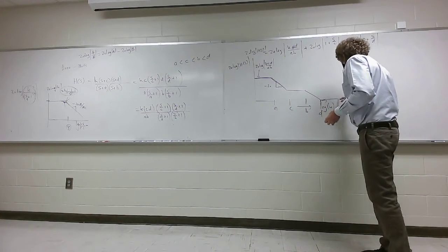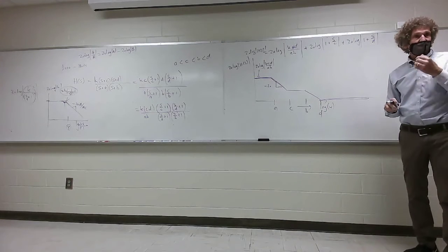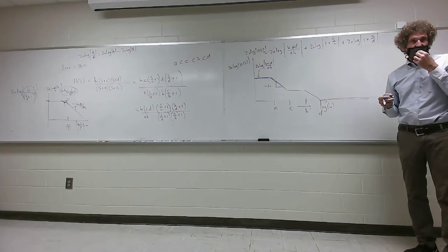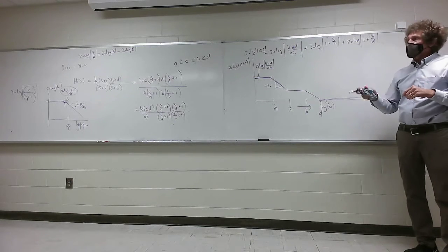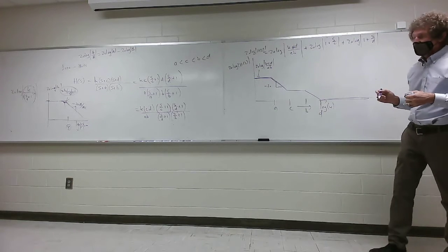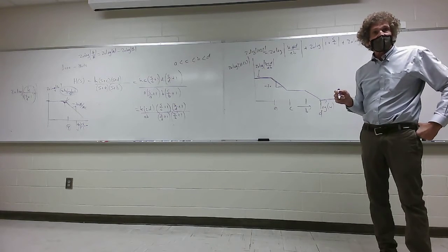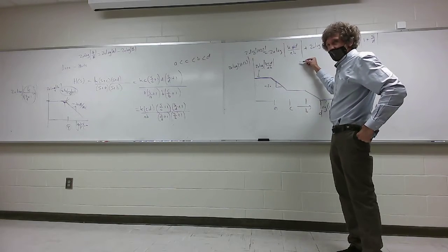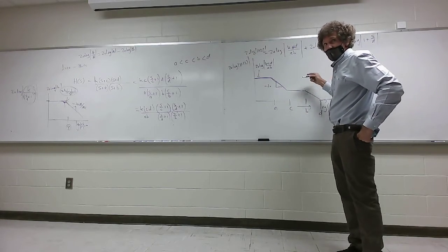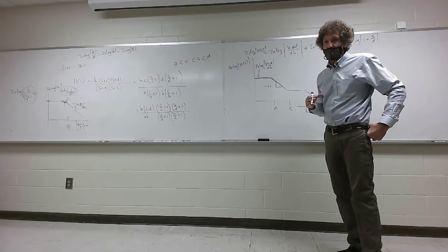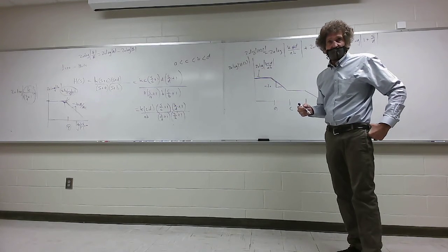Now, if I had to give that a name, it would look like a weird low-pass filter. To be honest with you, it's passing where the value's maximum at lower frequencies, correct, class? Y'all see how I could change those values, and I can have something different. Y'all with me on this? I can change these values, and I could have it going up and then level, right? And then come in. So you can play a game with A, B, C, D to get anything you want, from a notch filter, low pass, to a high pass filter. And we can keep on playing games here, but that's in essence what I wanted you to get from this.